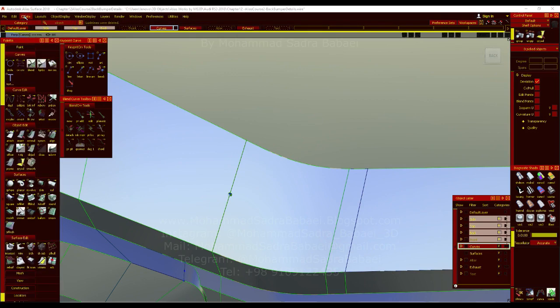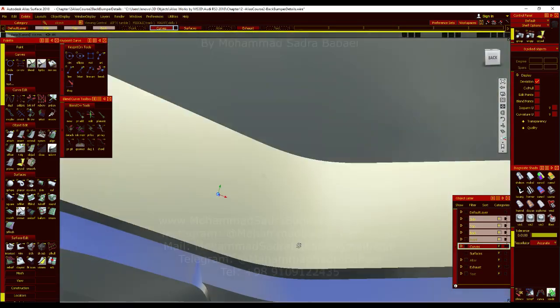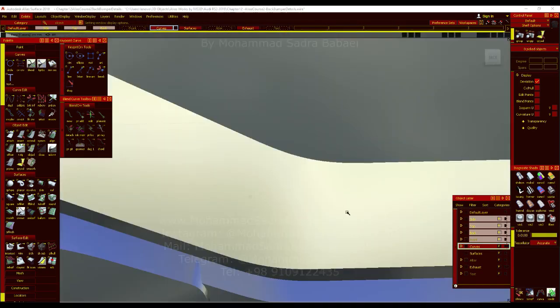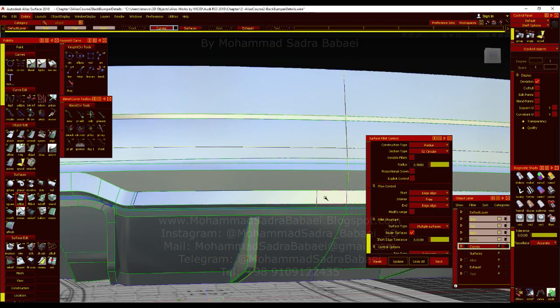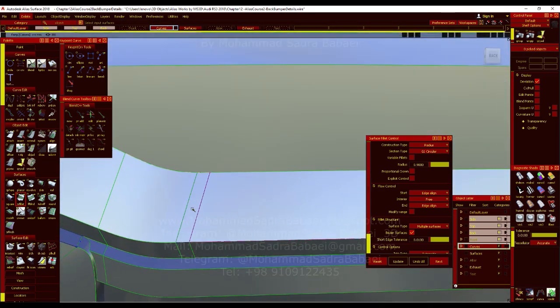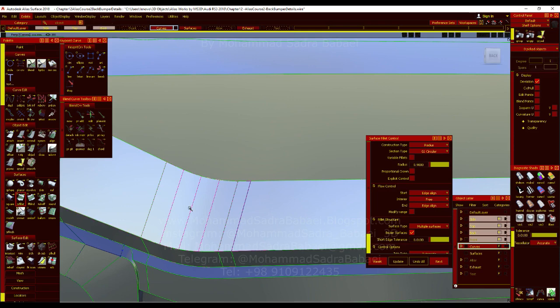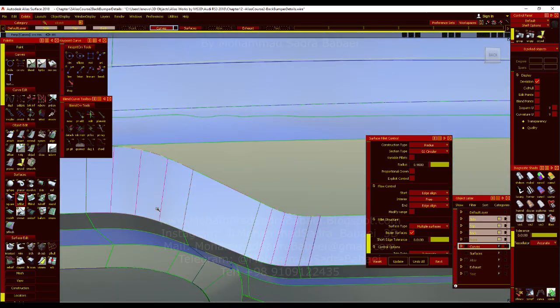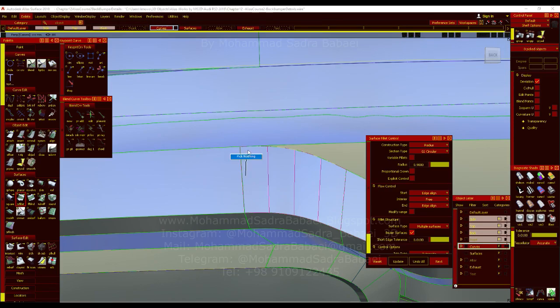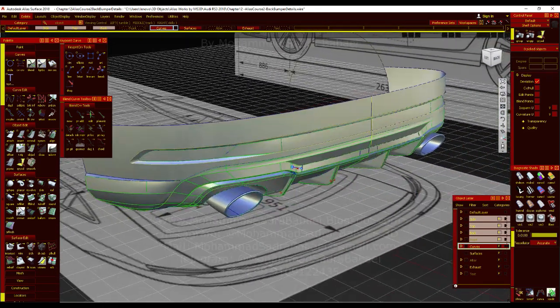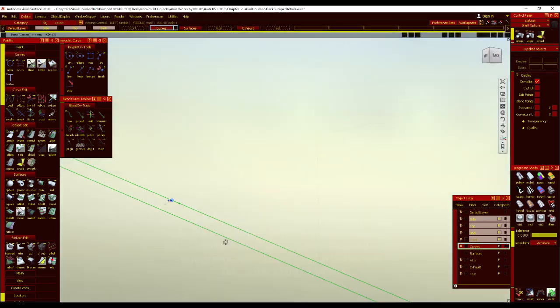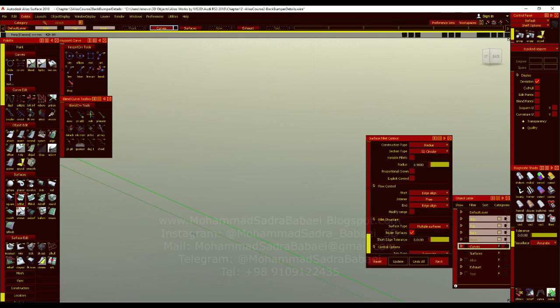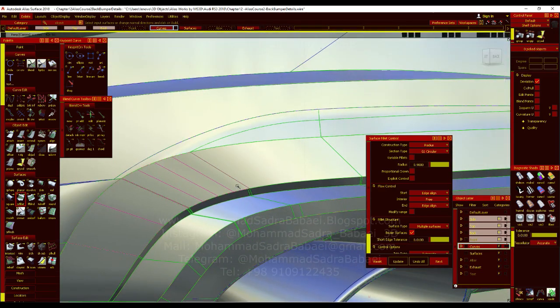You can also check that with locators, that we're gonna talk about later. It's okay, it's tangency. There's no very big difference in the hardware shading, but it is completely tangency, so they are all red. This one is yellow, so we have another problem here, so I'm gonna align that again. And don't forget these little surfaces. As you see, when we are selecting, if I select these two surfaces, one of them is going to color yellow.